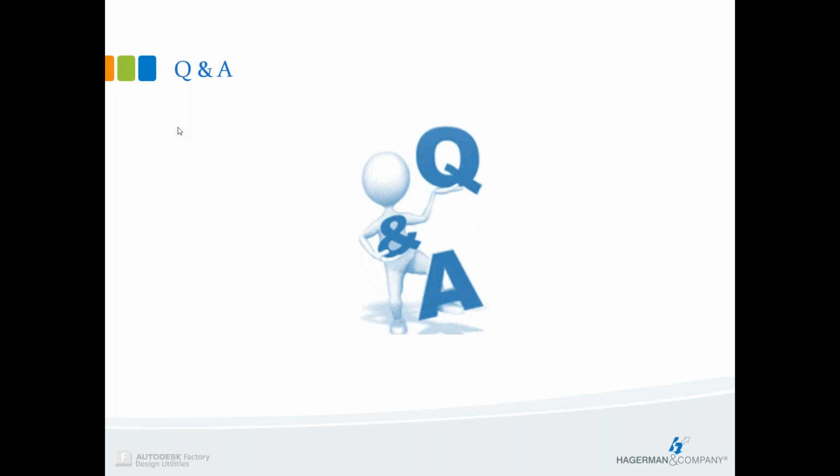So Wes has another question here. When one model is changed, does the relationship to the attached ones change as well? Yes, it does. So inside the software, as long as they are linked, it updates. If they are converted to standard models or the link is broken, then they will not automatically update. As long as they are linked back to the parent model, you'll get a notification inside of Inventor that your model that was placed via the AutoCAD solution has an update. Same thing on the Revit side. If I send Dan an updated model, he sees the little update icon there, he can refresh it and the model gets updated as well.